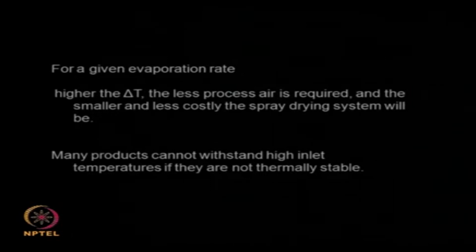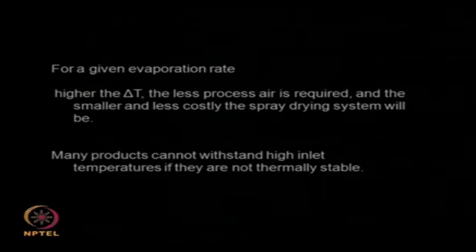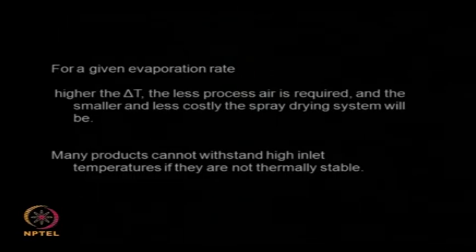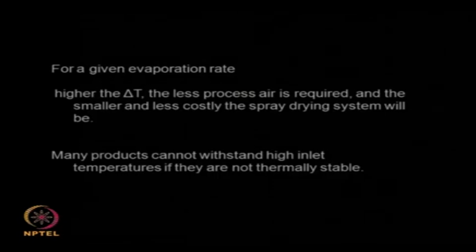One of the problems may be that the material which I am trying to dry might be temperature labile, that means it may lose its activity if you heat it up too much. So I can try to dry it with the high temperature driving force because my setup can be smaller, but I have to be very careful that the material does not get deactivated because of the high temperature. So you need to keep that particular point in mind.